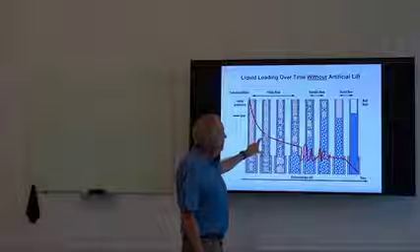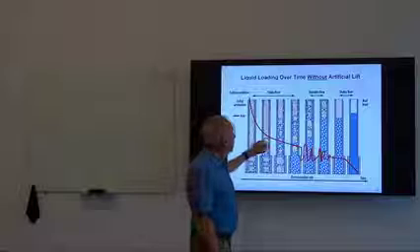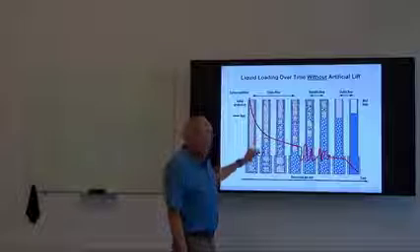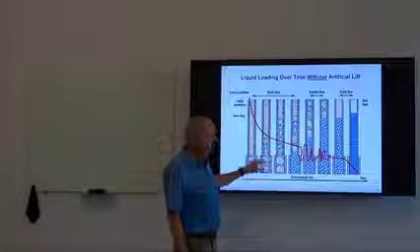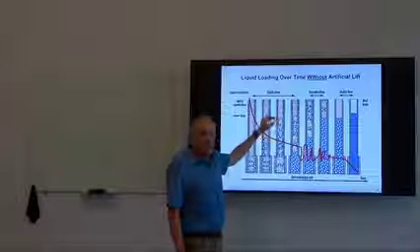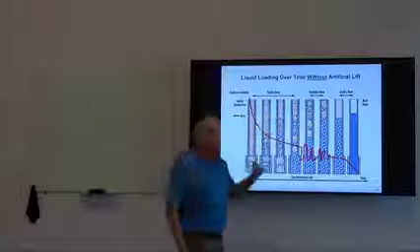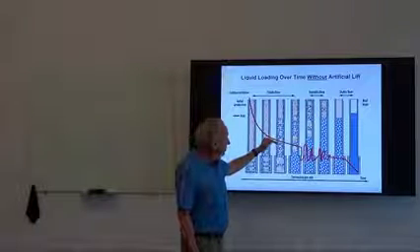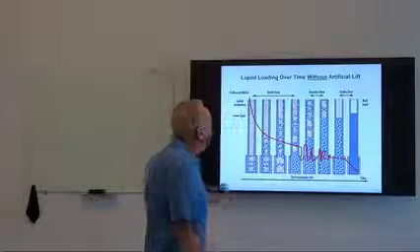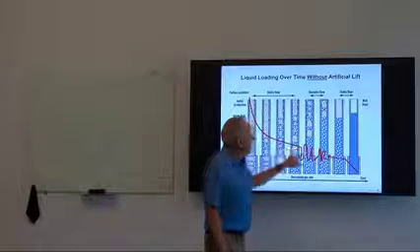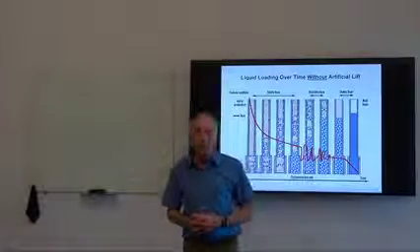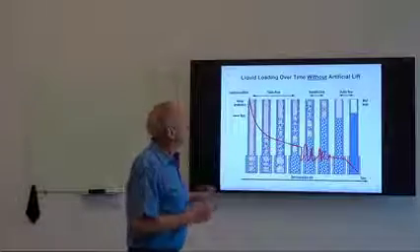The liquid builds up from the bottom of the well and starts to collect at the bottom of the well, and it starts to exert hydrostatic pressure back against the formation. Therefore, as this rate drops off and liquid accumulates more and more, actually the height of the liquid is reinforcing this reduction of flow into the well. And over time, we can see that the well will reach a point where it becomes unstable, or in some cases we would see this as slug flow at the surface.